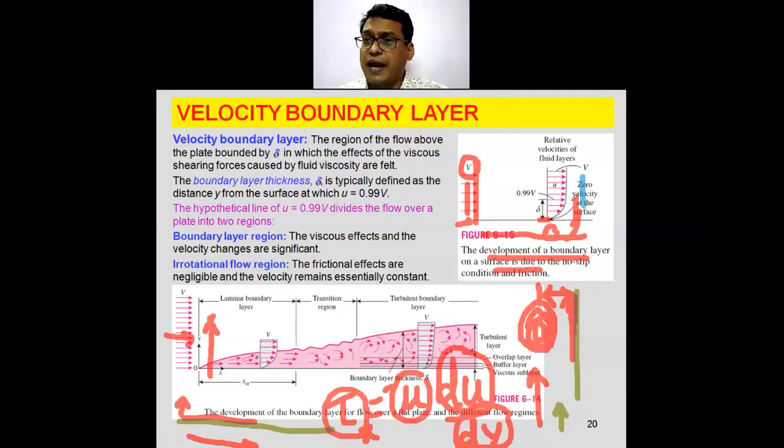So this is going to have a certain gradient in the lower region, and after that it may attain the same uniform velocity as that of the inlet region. So this region where the velocity gradient exists is of our concern. We are going to study this velocity gradient. Why the velocity gradient exists is because of the shear stresses, the fluid's internal stresses. The fluid's internal stresses are because of the viscous forces that are going to offer resistance in all the subsequent layers.